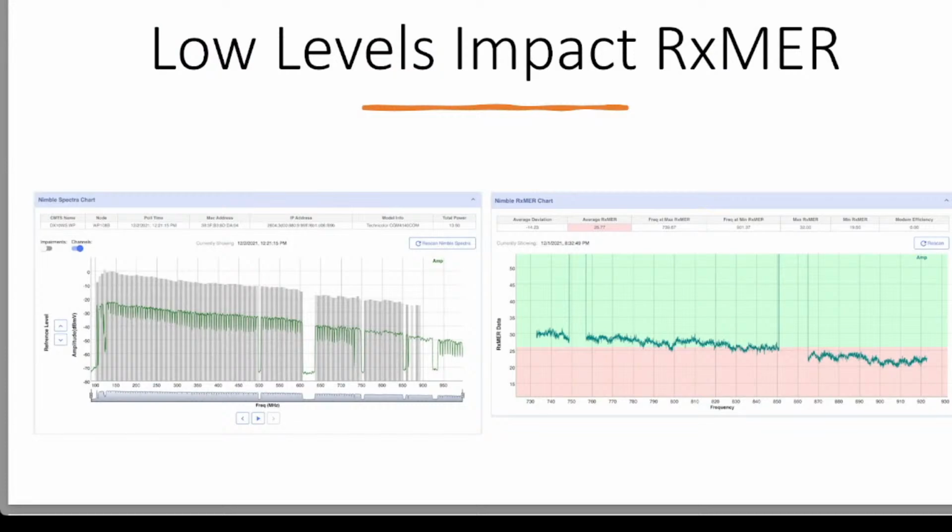So I'll put this slide up, and on the right-hand side we're showing full band capture. This is just an individual subscriber's home that is impaired. The rest of the fiber node was in great shape, but we have severe roll-off going into this subscriber's home. I don't have the answer why this subscriber had such bad roll-off, but there is something, and it is perfect tilt going down in. But yeah, exactly.